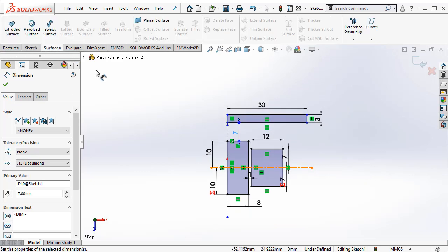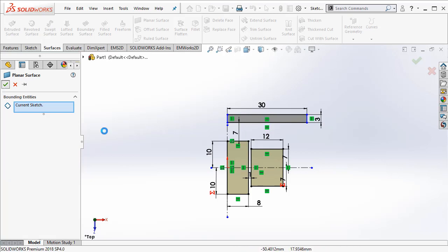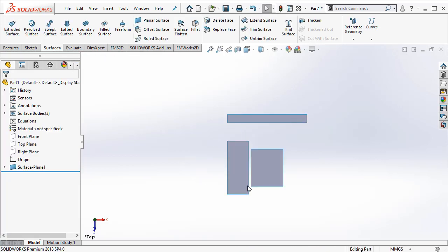So I will immediately go to surfaces and I create planar surfaces on this sketch. So what I have here is a core that is going to be made of a ferromagnetic material. I have a coil and I have a top plate. Now imagine these are not really 3D geometries. So imagine that I take this line as the axis and I revolve these three things. And that is really what represents our 3D geometry. Because we are doing a 2D simulation, which is going to be axisymmetric, we are just happy to do these things. Now let's draw the air geometry as well.